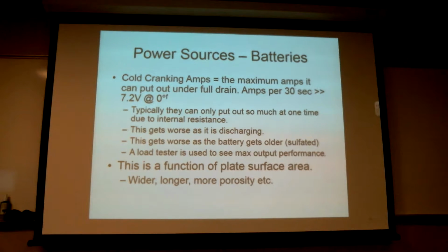Do you service those deep cycles the same way? A lot of your big marine deep cycle batteries are all serviceable, and they're intended to last quite a bit longer. They're pricey, like $400 or $500 a pop. How many amps do they draw? Their amp hours are going to be a lot higher. Cold cranking amps will be low, but their amp hours might be 300 amp hours. The big 8D cell casing.